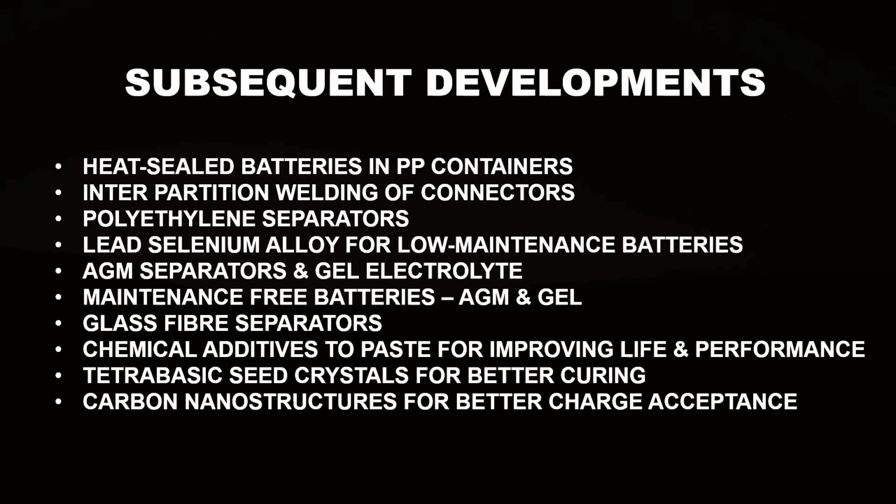The introduction of lead selenium alloy solved the problem of water topping up frequency. The development of this alloy enabled the reduction of the antimony content in the alloy. The water topping up frequency decreased as a new alloy was introduced, the lead antimony selenium alloy.